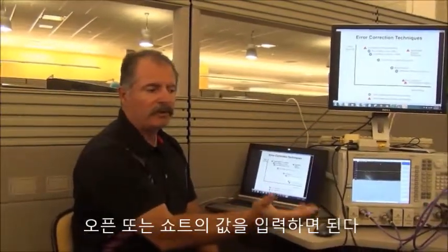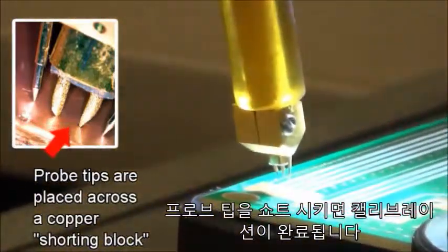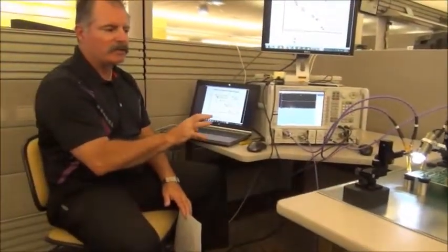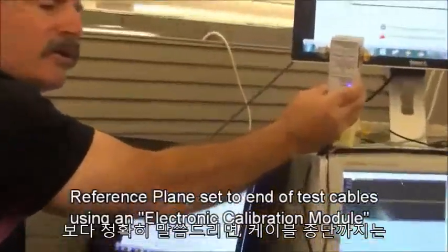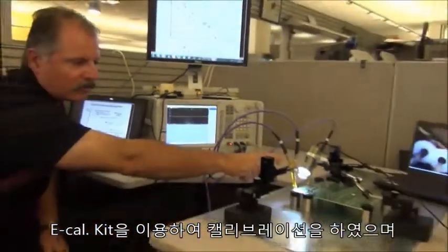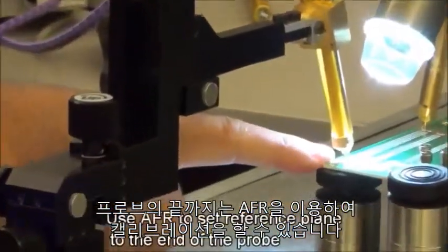For example, in our system here, we've got probes. We want the reference plane to be at the probe tip. So all we have to do is put a short or an open at the probe tip, and that's the calibration. To be more specific, we've first done an SOLT with an ecal, a short open load through to the end of the test cables. So we've got a coaxial environment with SOLT. But what we really want is the reference plane down here at the end of the probe tip.